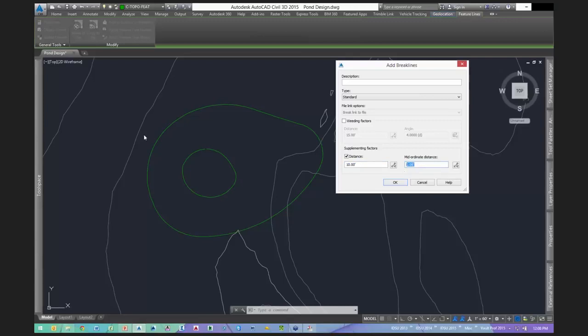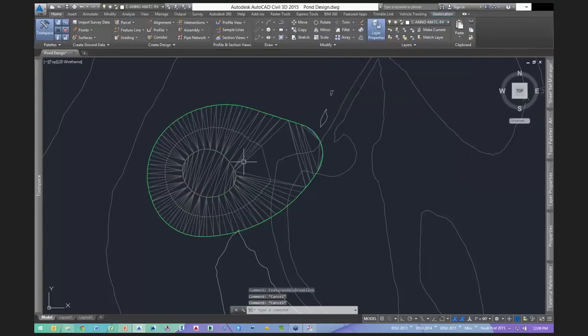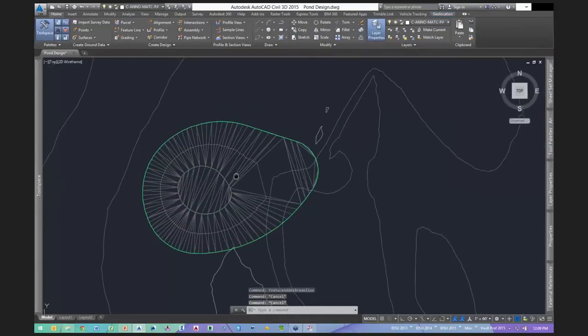In this case, all we have is curves. So this is really going to come into play here with how much it triangulates. And the translation is triangulation, the amount of it, plays a big role in how your contours look. They can also make your drawing real big, so there's kind of a nice balance here. Enough triangles to get decent looking contours. For a mid-ordinate distance, I'm going to start out at 0.2. Okay, I'll hit OK. So what mid-ordinate is specifically?